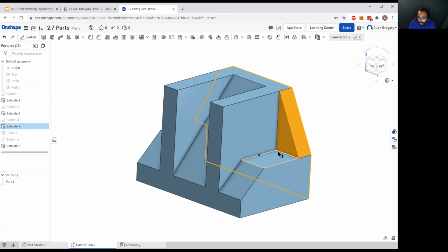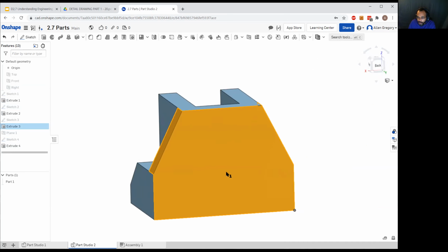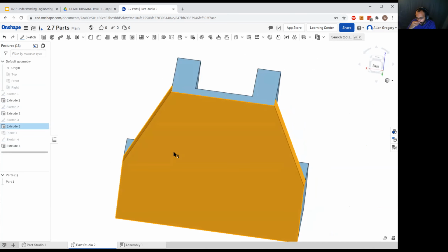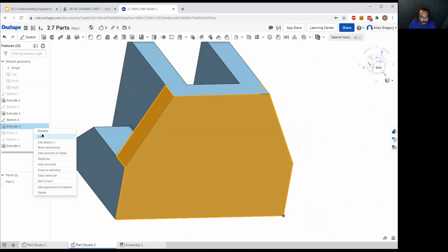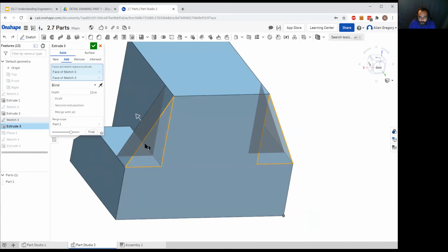Okay, backing up a little bit. So the triangles on the side, we did on a sketch on the back. So we just made a sketch on the back that was just these lines here, but if you draw them properly, Onshape will do it for you and understand that that shape can be closed off. If for some reason it's not, you can draw out the full triangles, and then you just do extrude with the add button, and it adds them in to the right spot. And if they're going the wrong direction, we can flip them around to be in the right direction.